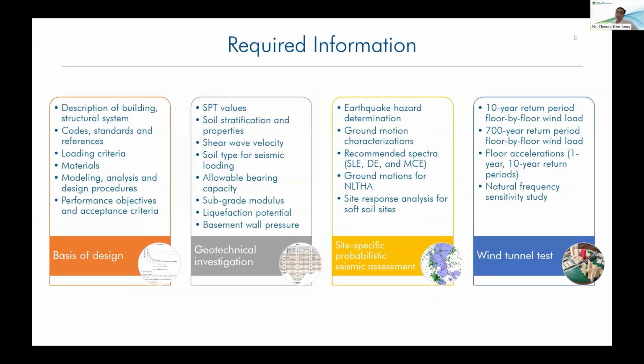To conduct PBD, we need additional information compared to the building code-based design. First, we have to prepare the design criteria. That part we normally prepare in the code-based design as well, but we need to add additional items in the design criteria, considering the nonlinear modeling procedures and also acceptance criteria for different levels of earthquakes.